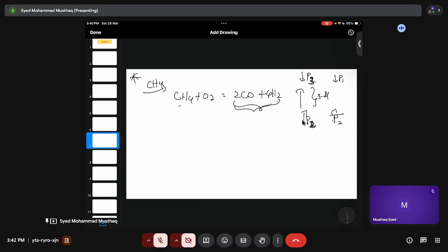But this reaction is a cooling reaction. It's an endothermic reaction, so it will cool your blast furnace at the tuyere level, right? Which is not required. So that's why we do not use complete steam. So that's why we introduce oxygen, but with that we also introduce hydrogen or methane.